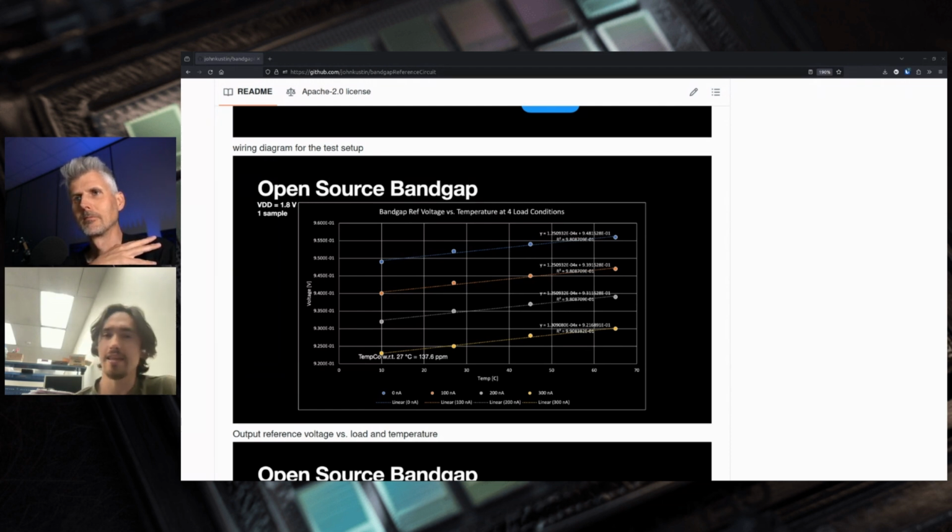Even in your mind, just create a fake scenario of, this is going to set the common mode voltage for some amplifier, and maybe it's a bunch of amplifiers, and you use that assumption to just pull out a number. All you need is a starting point, and going from there to establish your own spec can help. It would help me realize a more robust design.